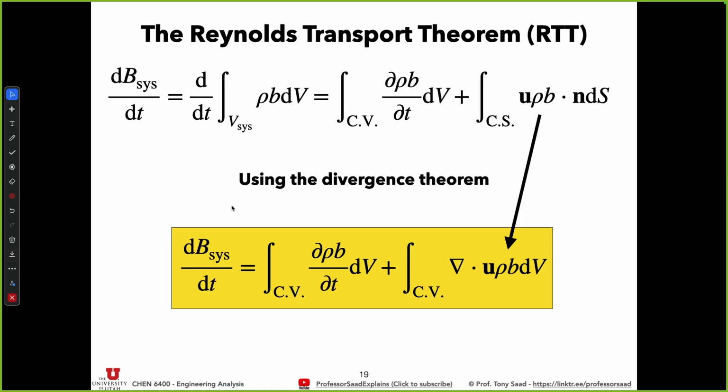It's, in the end, it's a math conversion and integral. Okay. It's a Leibniz formula. That's what it's called. But in fluids, we call it the Reynolds Transport Theorem because it's focused on having a fluid flow, a velocity field. The simplest way to think about it is say, this is just a formula to go from the conservation law of a material system, Newton's law, the first law of thermodynamics, to a form that doesn't follow a material, that just looks at points in space.